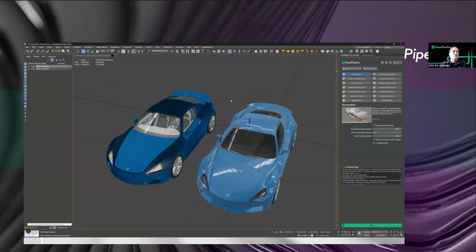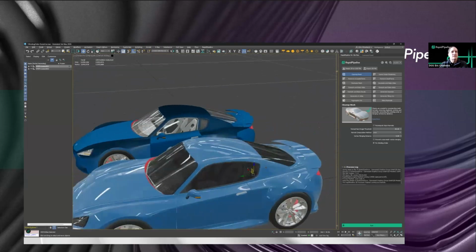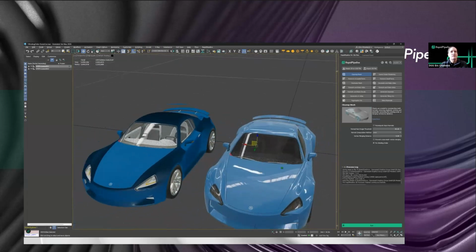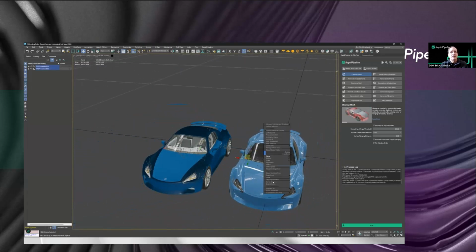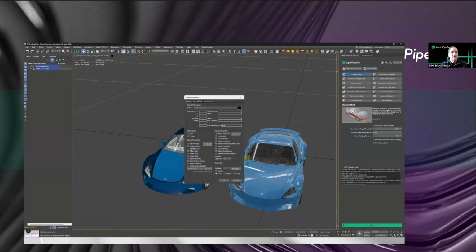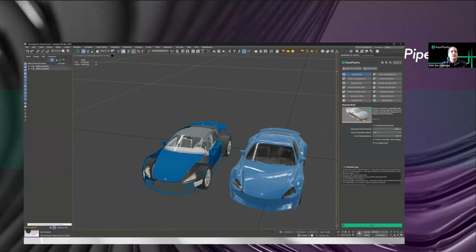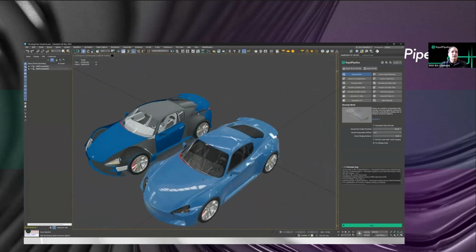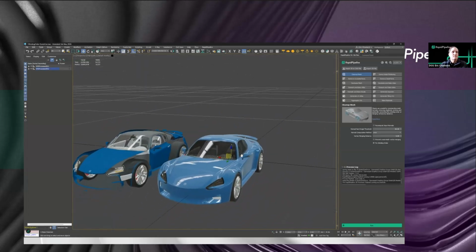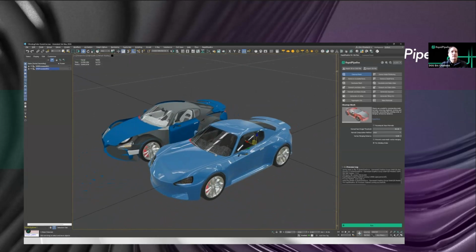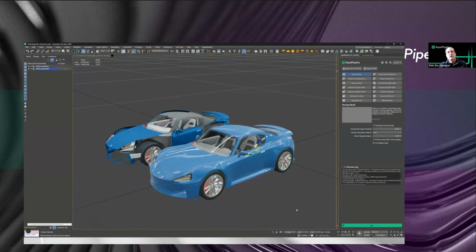So it's non-destructive, which is cool. And here it's showing us the fixed model. If we select everything, go to Object Properties, and say cull the back faces, we can see it's automatically fixed all of those for the model. So it looks great. So that's Fixed Winding Order. It's a great tool to have. I don't have to do this all manually and fix all those individually.